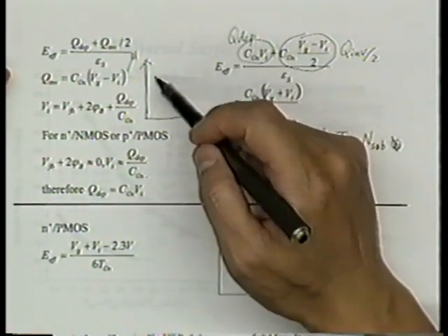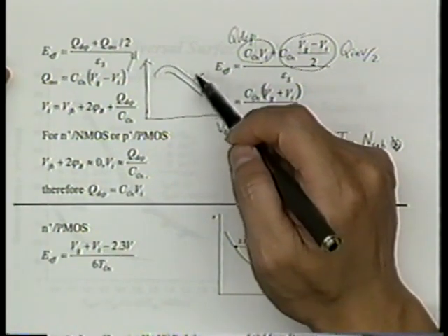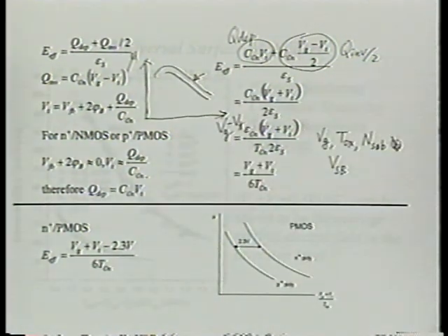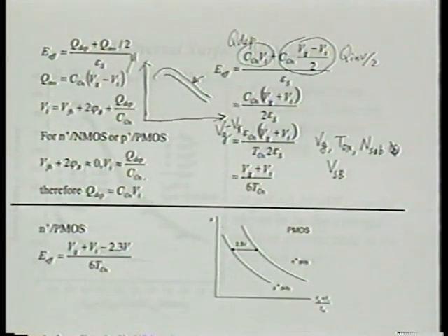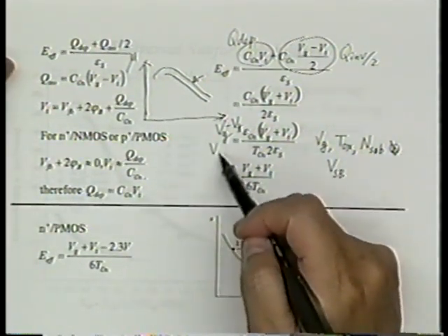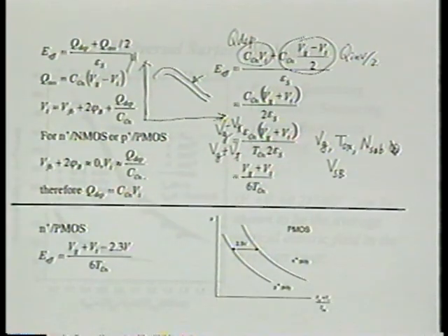And they will find one is a little higher than the other. Do you know what they're going to conclude? They say this technology has better mobility. And you better believe this usually is the one that he's proposing as his new idea. This is the control. Now, in reality, of course, it's a very different result if you plot this against VG plus VT, which is the proper way of doing it. Do you know what I mean?